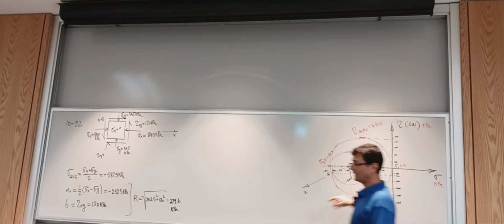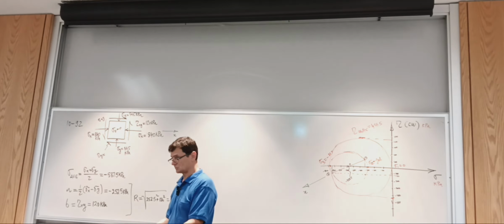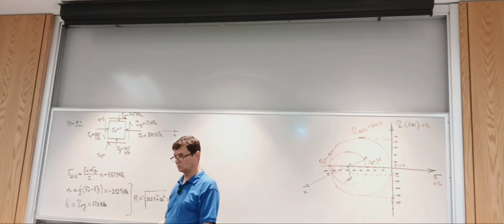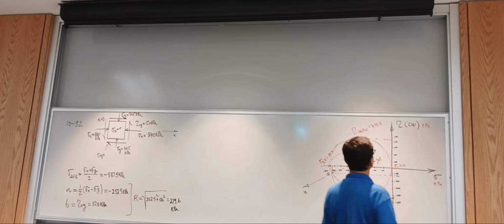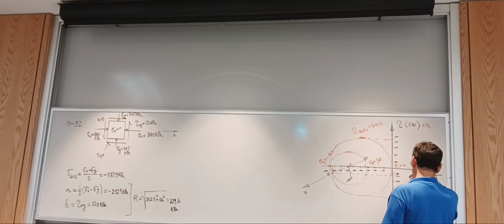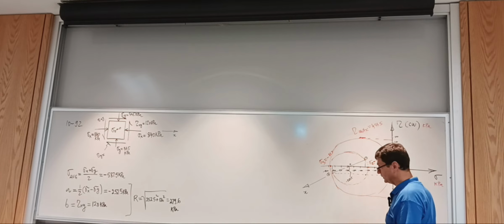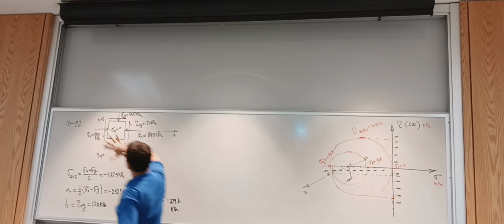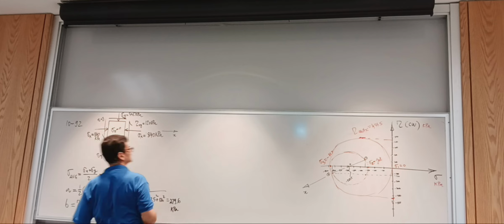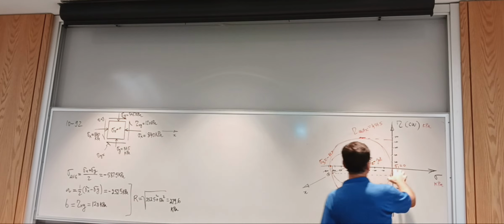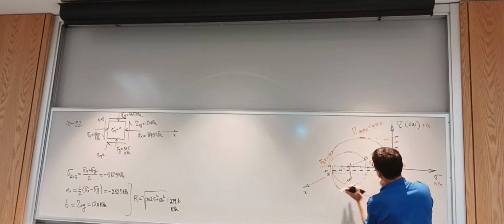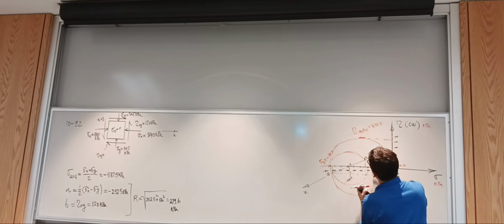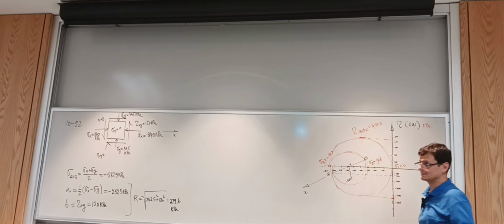If I have this submersed in a compressed fluid, say a hydraulic system, and I have 100 kilopascals of ambient pressure compressing the surface, then sigma 1 is going to shift to this point. The 3D circle becomes smaller, tau max becomes less.